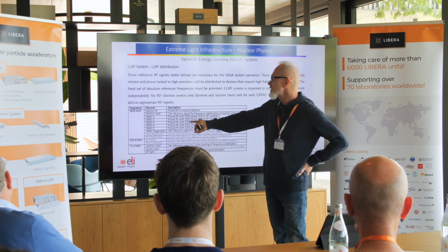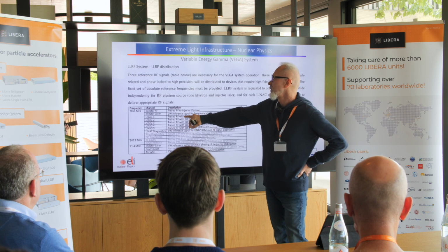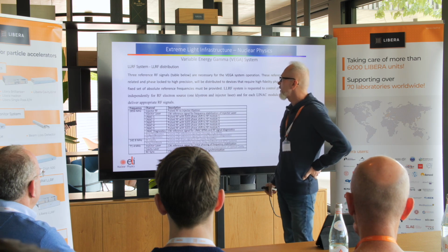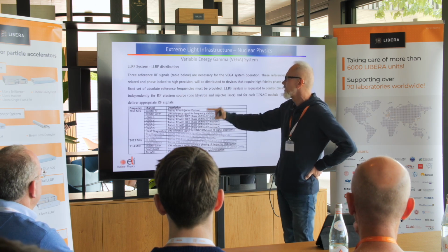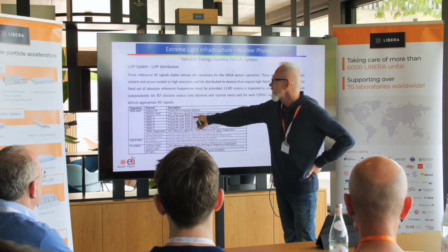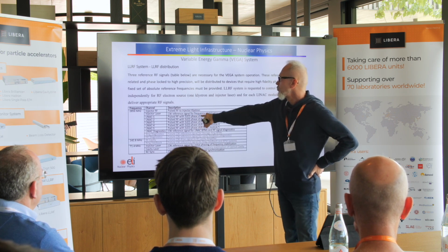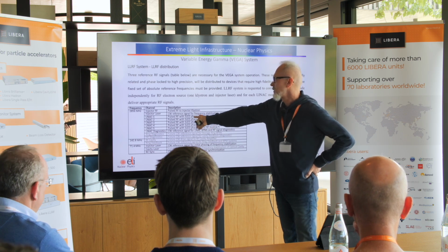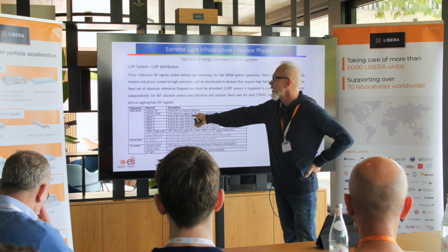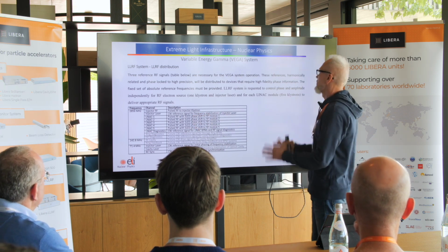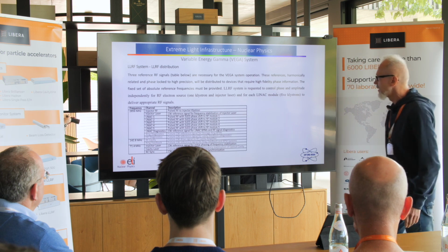So in order to do this, we have to give a signal for the modulator, which will be amplified by the klystron and later on by the SLED. But we have to keep in mind that we have to do this fast phase shift at the klystron signal before the SLED is compressing and raising the signal.